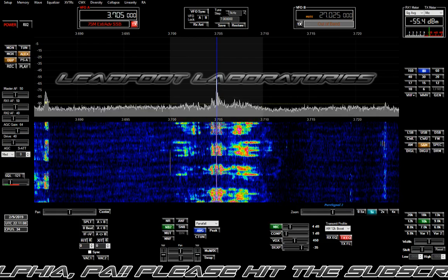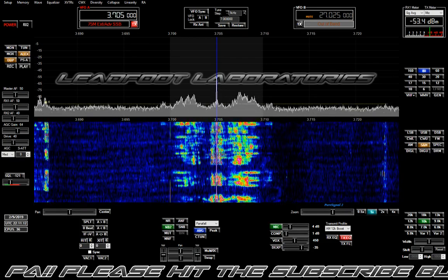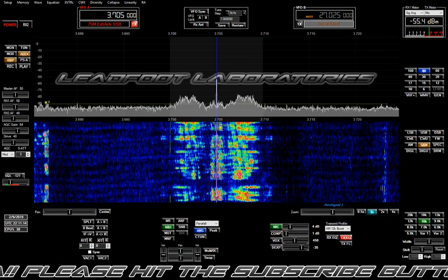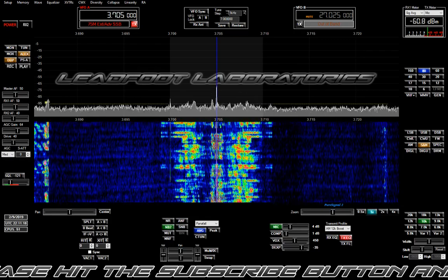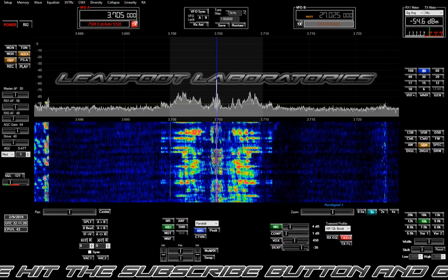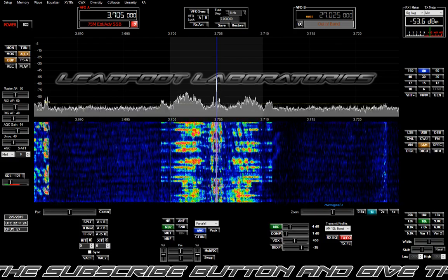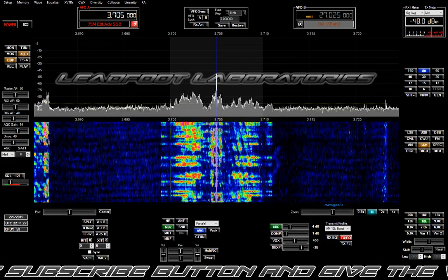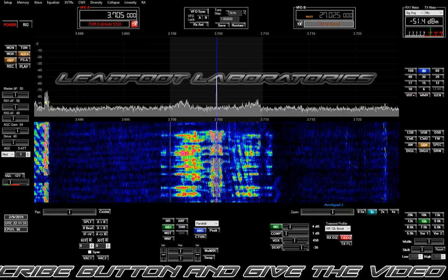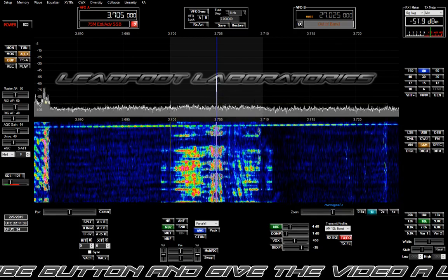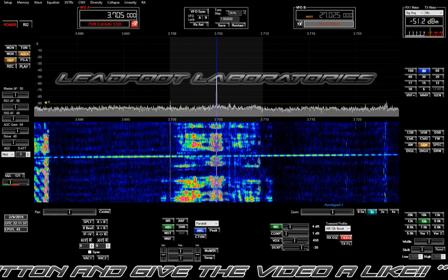And this particular LDMOS amplifier has very, very low distortion. So I think the combination of running everything well within its limits with lots of extra headroom is the key to a clean signal in everybody's technology, whether it's tube technology or solid state technology. Headroom is what it's all about. So, you don't want to run anything right up to the limit.